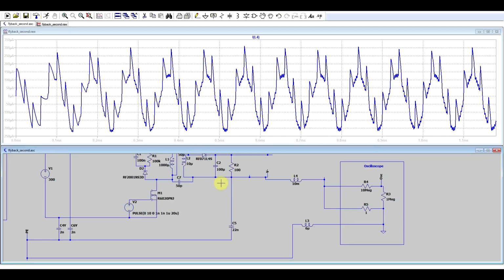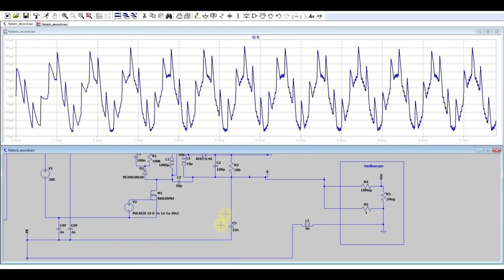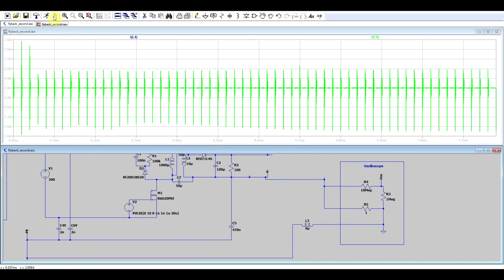But again, this is not something that you can really do, especially since the supply is a 5 amp supply. So you need to make a 10 millihenry inductor that can handle 5 amps. Now of course 10 millihenry is not really necessary, but you would need a high inductance to actually filter this out. But a better thing that can be done, without actually overcomplicating the supply, is work on this output capacitor. So the capacitor that's connecting the output to the protected earth. Now at the moment it's at around 20 nanofarads. But let's say we increase this to 400 nanofarads.